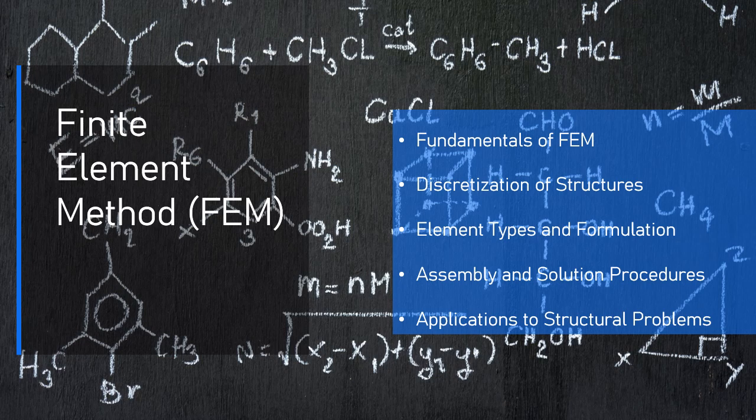2. 2D elements, surface elements. 2D elements are used to model structures like plates, shells, and membranes, which primarily experience bending, in-plane stresses, and shear. These elements are used in thin structures, where the third dimension can often be neglected.